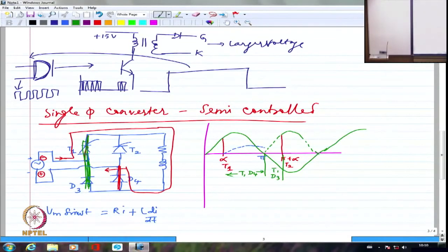See, potential difference we have to look at. We cannot look at only anode potential. With respect to the cathode, whether it is more positive. That's what we have to check. So if the current is already flowing, there is a small voltage drop, 0.7 or 1 volts or whatever. That will always be plus here and minus here. Because a thyristor can never conduct in the opposite direction, obviously.